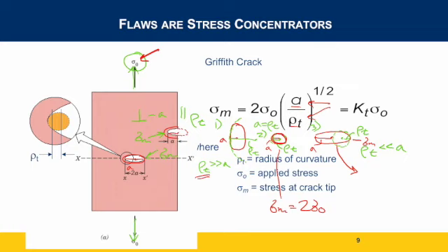It has very high localized stresses. To release that stress, the crack propagates, and it keeps propagating very rapidly. So this would be basically a crack in your windshield. Something like a pebble hits the windshield, and the crack propagates in both directions. They typically will propagate perpendicular to the stress. So when we're defining that, we're basically drawing the crack as a very shallow ellipse, like this, right? So my rho sub t is tiny, but my A is huge. And that's where I get crack propagation.